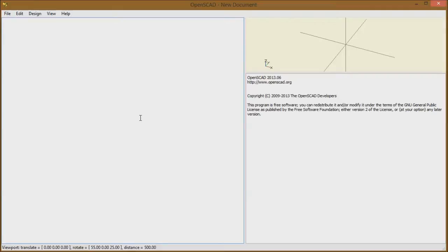So to that end, let's start with, if we had to make this bracket, we can assume that the two sides that are attached to the piece you want to hold at 90 degrees would be the same length. So let's start with creating a variable called height width, and let's make that equal to 40. Maybe this is a good time to mention that in OpenScad you don't have units in terms of normal metric units, millimeters, inches, whatever. You only have units.